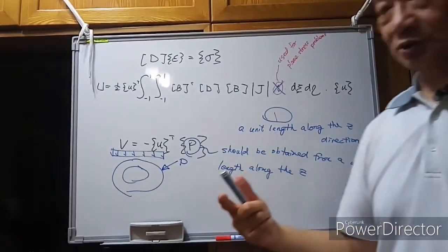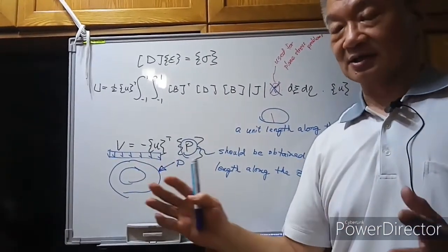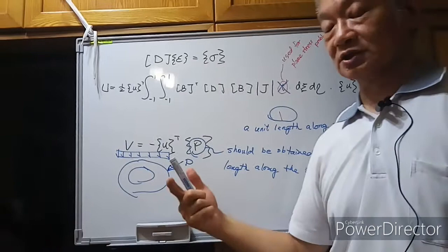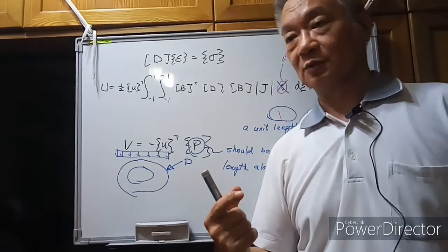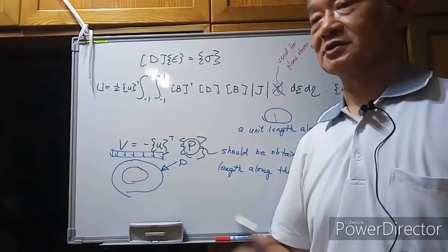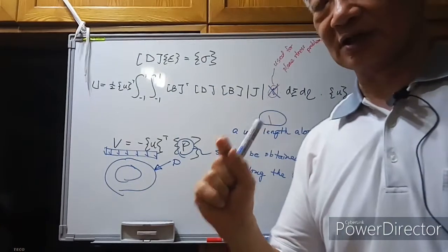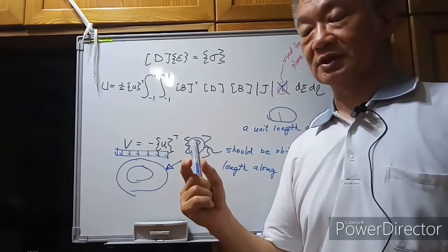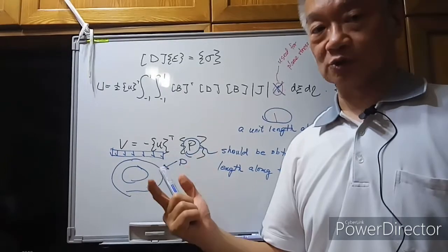When we output the results, we need to output the nodal displacements. They are exactly the same for both models. And when we output the strains and the stress for each element, for the plane stress problems, you can output the 3 non-zero stress, but you can output the epsilon z, the fourth non-zero strain. That's the epsilon z. For the plane stress problems, you can output the 3 stress and the 4 strains.